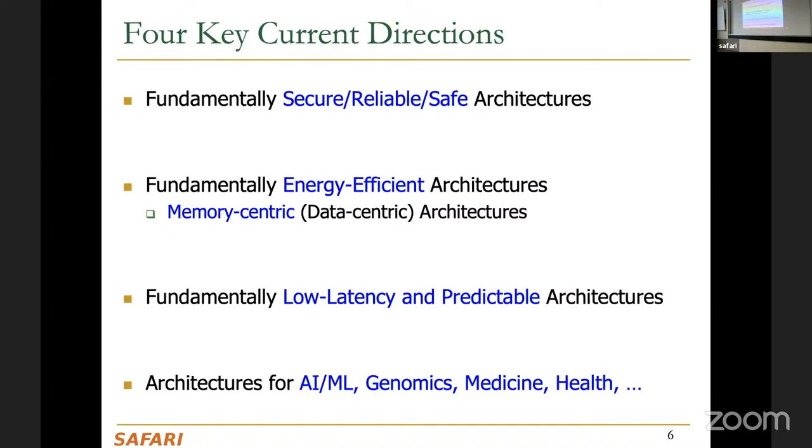Today, basically, you have the processor here, memory here. Get the processor closer and closer and closer to memory. It could be inside the memory chip, it could be near the bank, whatever. But as long as you add logic, that's processing near memory, or logic near memory. This is very fundamental, I think.